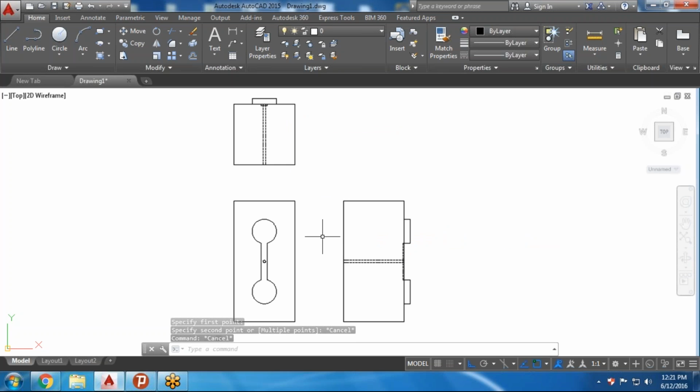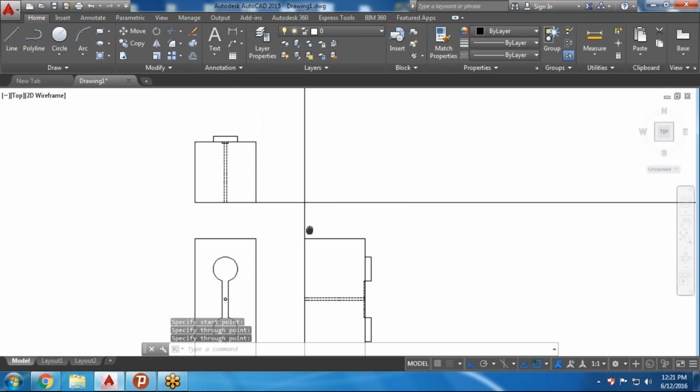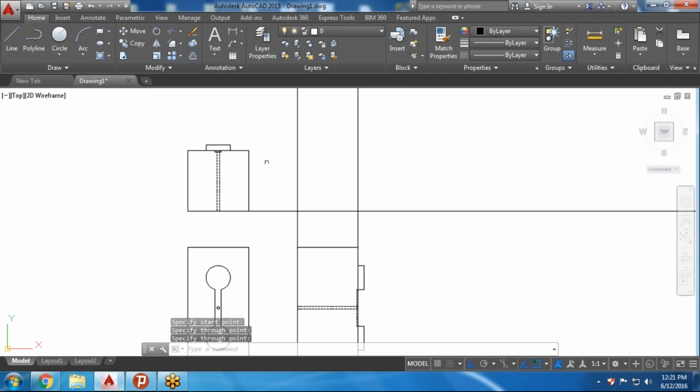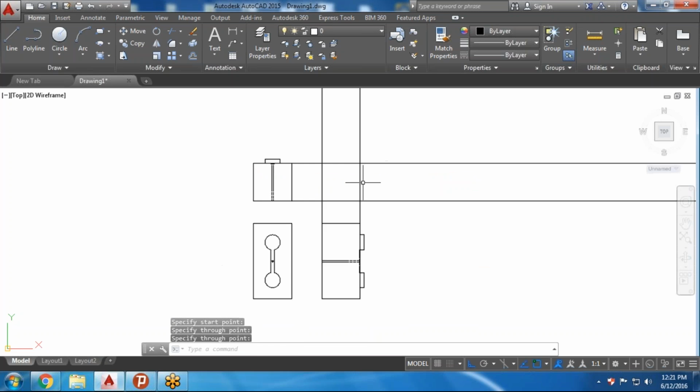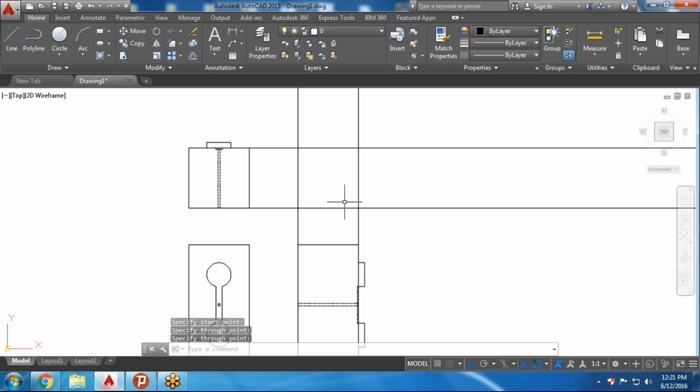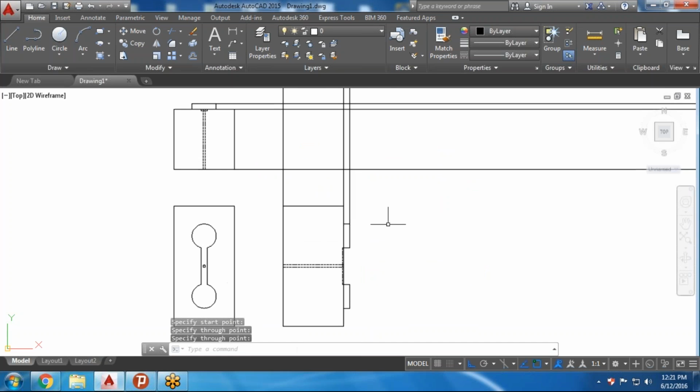Whenever I create all these things and we have accomplished this, now we have to justify this. So just use ray, RAY, start from this point upwards, and this like this, and now after that click this, create a profile like this. This should create a square profile. Done. Now this will go up and this will go right, and that's all.